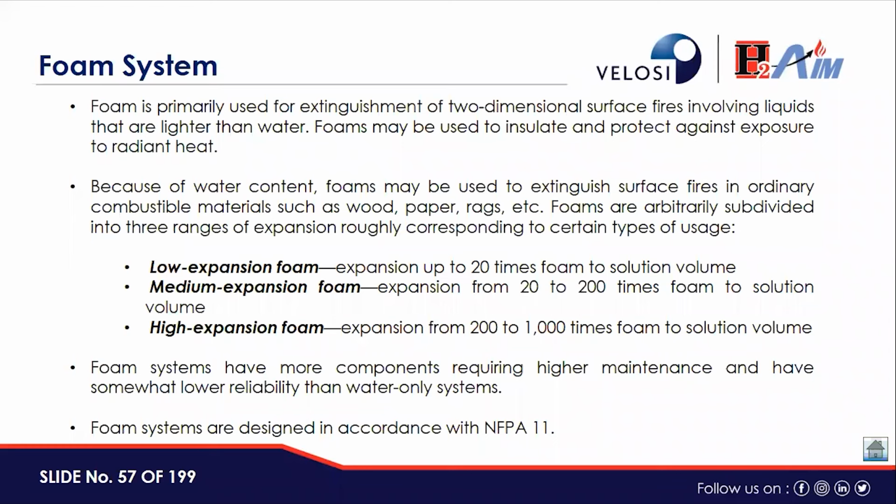So what is the volume of low expansion foam? Expansion up to 20 times the foam to solution volume. Medium expansion foams are the expansion from 20 to 200 times foam to solution volume. And high expansion foams are the expansion from 200 to 1000 times foam to solution volume. Foam systems have more components requiring higher maintenance and have somewhat lower reliability than water-only systems. Foam systems are designed in accordance with NFPA 11.